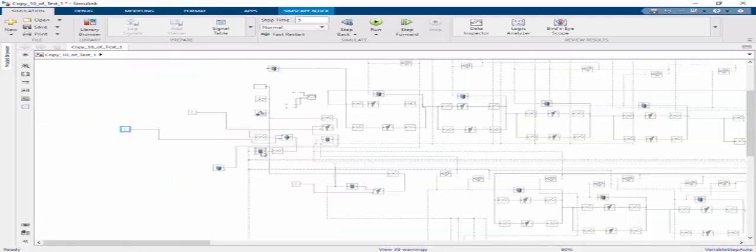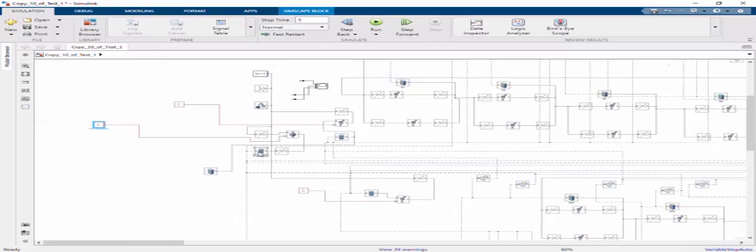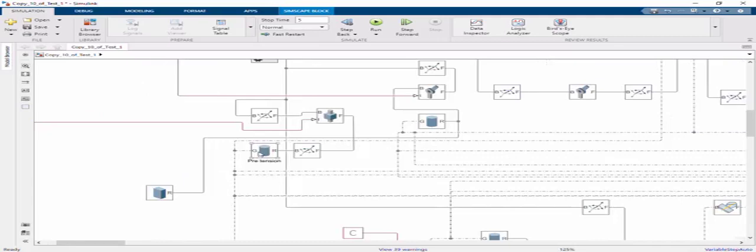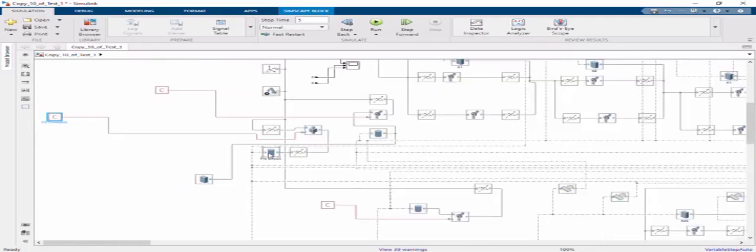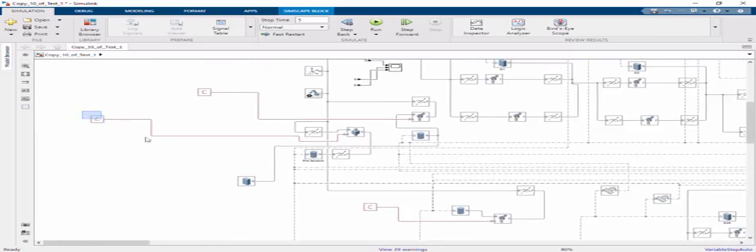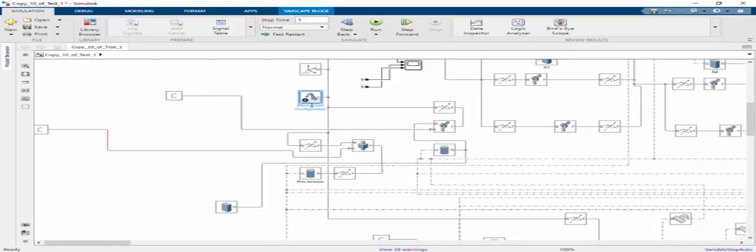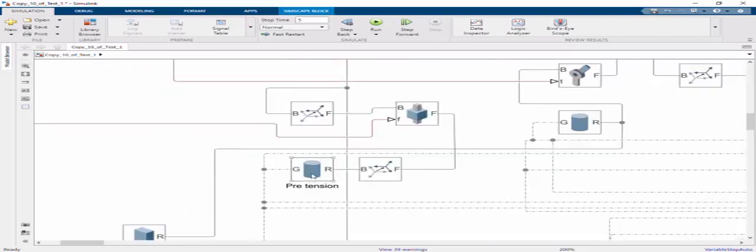so that I can have some initial tension on my belt conveyor even before getting it started by the rotating pulleys. It is important to notice that it was also possible not to use this block and this force here, because the gravitational force that I already configured in my mechanism configuration gives me enough force to move the pretension weight downward.